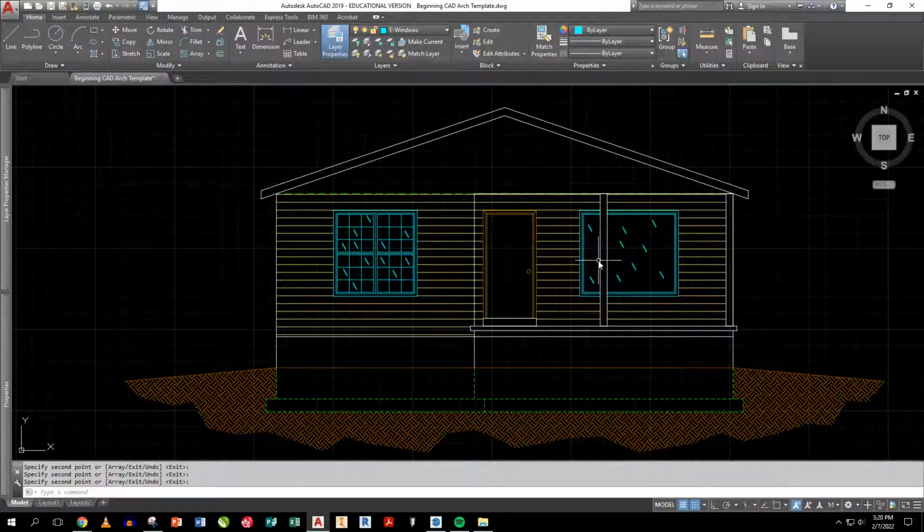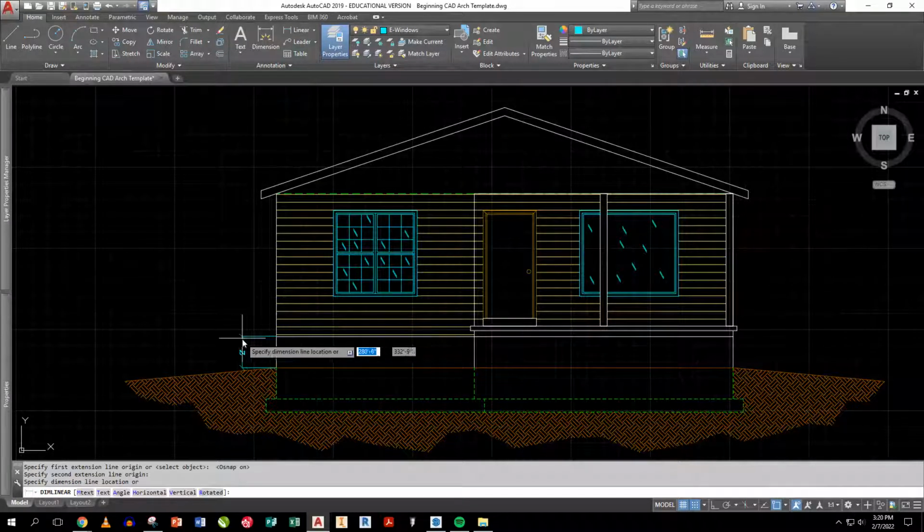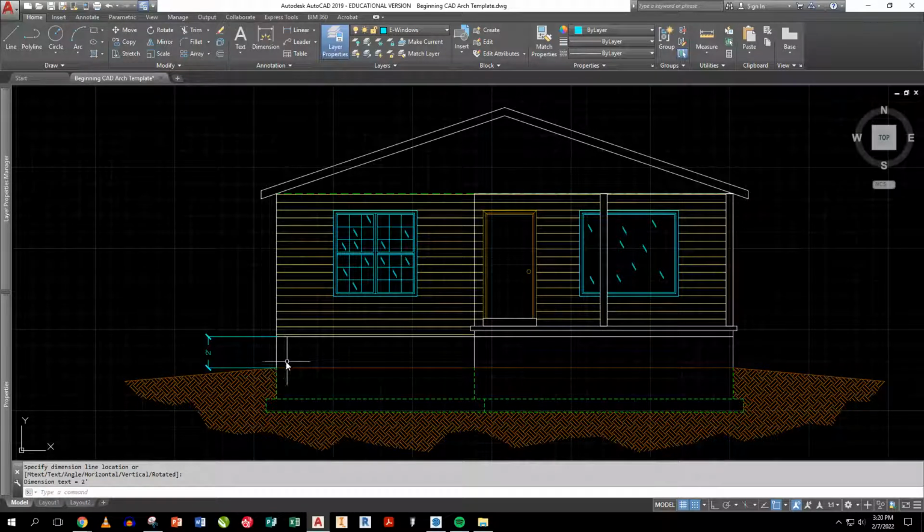Now the important part is the dimensions on this. Dimensions get interesting on this. We don't use a normal dimension tool. In normal dimensioning, I would go over here to my dimension tool, linear, and I would turn my O snap off and measure from here to there, and pull it out here, and drop it off, and then I'd go okay. Let's continue those.